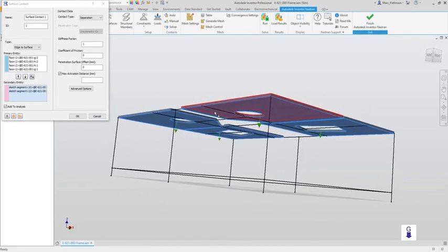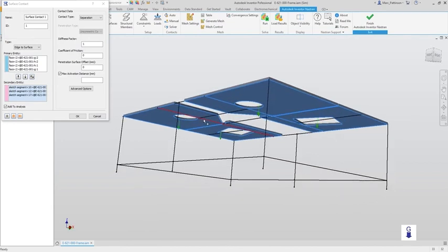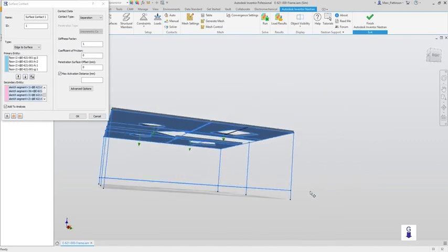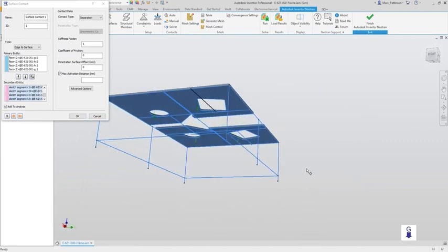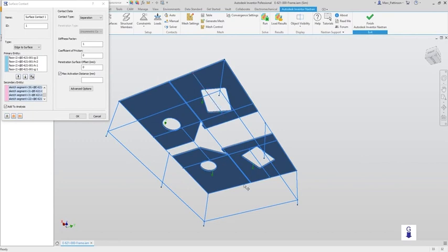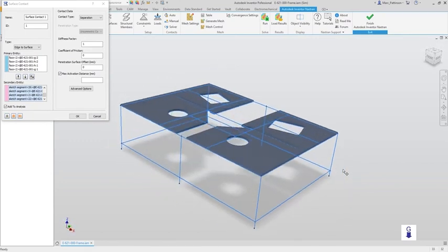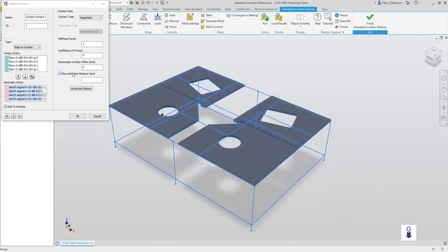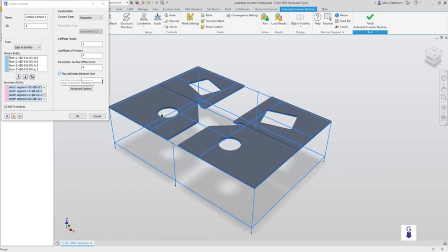Now, making this look as clumsy as possible, I will select all the different lines which represent our beams, and I've also selected the bottom faces of our model. We can window select, and we can click and select. Once happy that all objects have been selected, missed one. When we're happy with that, we're now going to specify the max activation distance to be 20 mm.